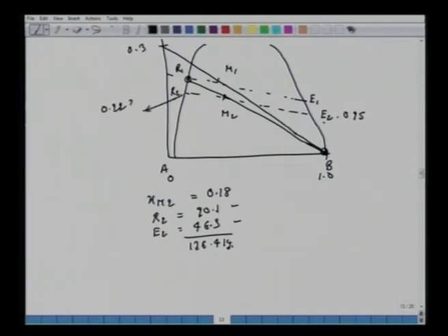Okay. In this case also you can note down the third stage. xM3 will be equal to 90.1, that's what we had, into 0.227, plus we have a fresh amount of solvent 40 into 1, divided by 90.1 plus 40, 130.1. This will give us 0.1572.